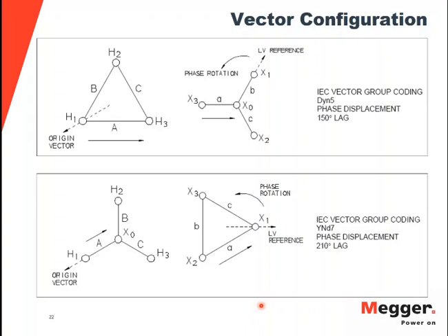The first, we can mention the TTR test, where you're getting your turns ratio, and you can compare that to the nameplate. And of course, if you have factory test values and commissioning values, you can compare to that. So that's one nice thing, you have a direct, on-the-spot comparison all the time with those nameplate values.